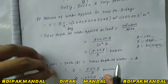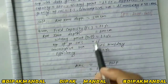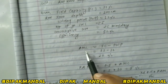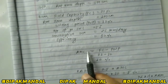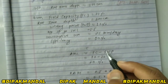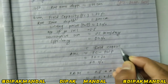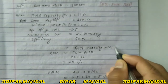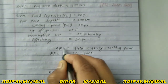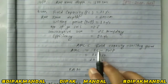Okay, now let's see the solution of the numerical. So we have been given all this data. Now we have to calculate the value of AMC. Simply, the value of AMC can be calculated by subtracting the wilting point from the field capacity.